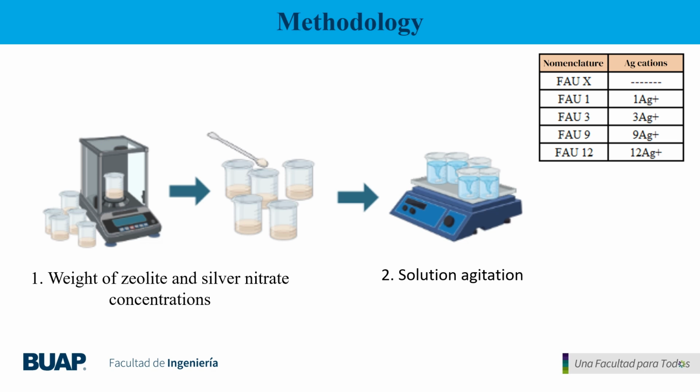For the first phase, we use VX zeolites. Zeolites are microporous aluminosilicate minerals that have the capacity for cation exchange. We want to take advantage of this property and exchange it with metallic particles, in this case silver, and promote inhibition on the textile. For this, we make different concentrations of silver on the zeolite and we have named the samples depending on the number of cations exchanged: V1 for the sample with the lowest quantity of silver cations and V2 for the samples with the highest silver content.